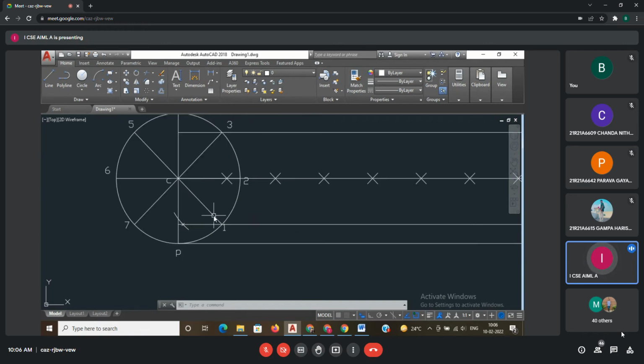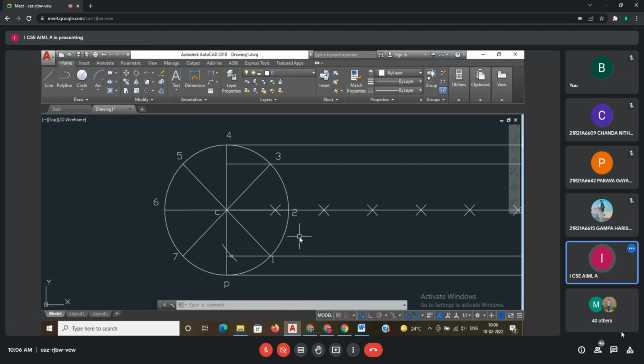Okay. Suppose here you will clarify one more doubt. I told you that whenever the rolling circle rolls in the clockwise direction, you are taking notations in the anti-clockwise direction. Suppose if you take notations also in the clockwise direction, what will happen? Suppose instead of 7, you will have 1. Okay. So go here, notations. So here it is 1, it is 2, 3, 4 same, it is 5, again we will give here 4, 5. Here is 6, here is 7. Okay.